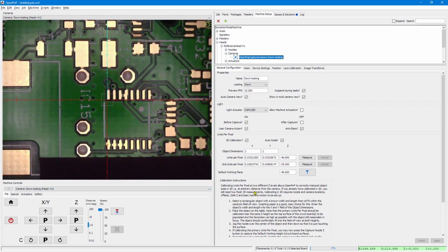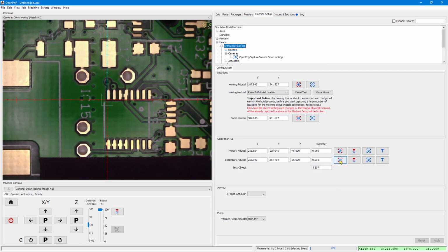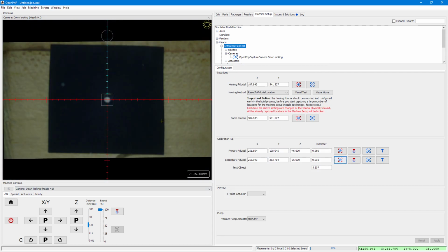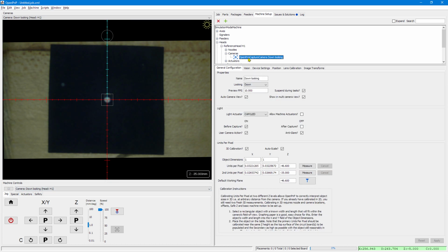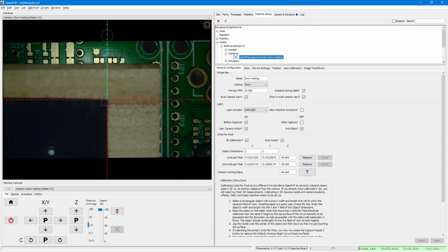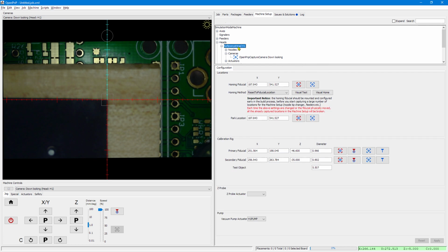And the clue of the 3D calibration is that you can go to the higher level, and because the camera also knows the Z coordinate, it can now calculate the correct units per pixels and again do the graphical jogging with precision. You see it even jogs precisely on this elevated level.